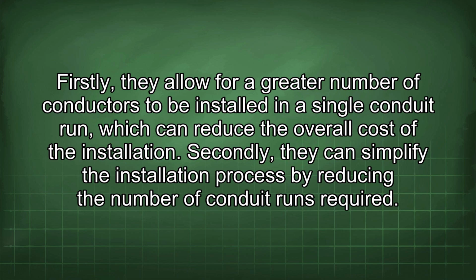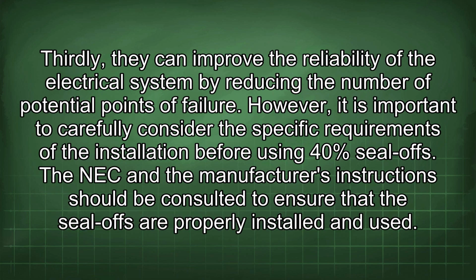Secondly, they can simplify the installation process by reducing the number of conduit runs required. Thirdly, they can improve the reliability of the electrical system by reducing the number of potential points of failure. However, it is important to carefully consider the specific requirements of the installation before using 40% seal-offs. The NEC and the manufacturer's instructions should be consulted to ensure that the seal-offs are properly installed and used.